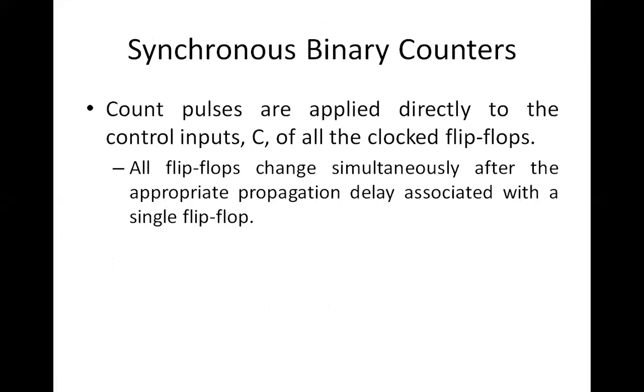Okay. So in synchronous counters, the most important thing is that the count pulses are directly applied to the clock inputs of all the clocked flip-flops. So here, all the flip-flops change simultaneously. That's important. It is not waiting for the previous flip-flop. All the flip-flops change simultaneously after the appropriate propagation delay associated with a single flip-flop. Right. So this is important.